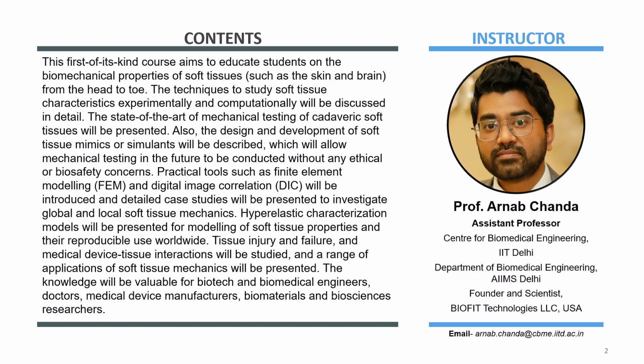This could be skin, this could be the human brain. Every form of tissue in different organs from the head to toe, right? The techniques to study soft tissue characteristics experimentally and computationally will be discussed in great detail. Okay, so what are experiments? Experiments are all the mechanical characterization techniques like compression, tension, cyclic loading, shear loading, using an indenter, finding out what are the properties of the material, right? All these things would be covered, as well as you will be looking at the computational modeling aspect.